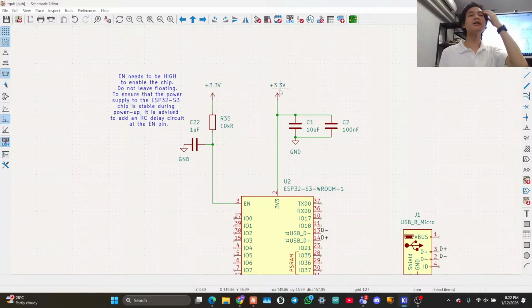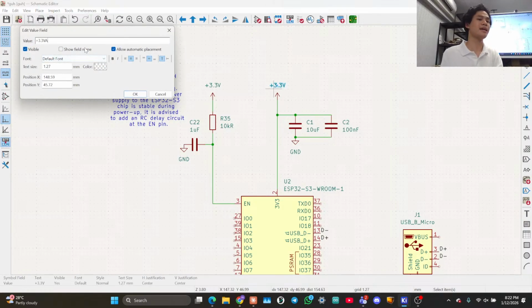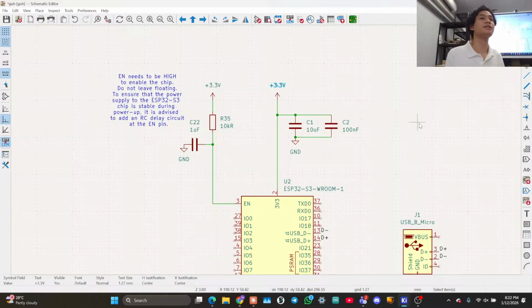Sometimes on circuits with digital and analog signals, maybe you will have a different power supply for digital and analog, because analog will need a cleaner DC input. So then you would name this 3.3 volt A or something for analog, and now they would be part of different nets. But usually, at least for digital electronics, we only have one power supply, so it's fine.